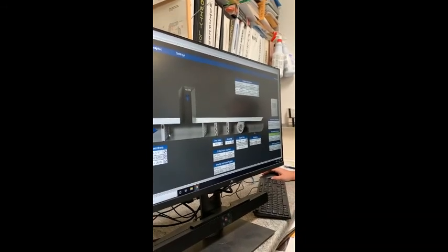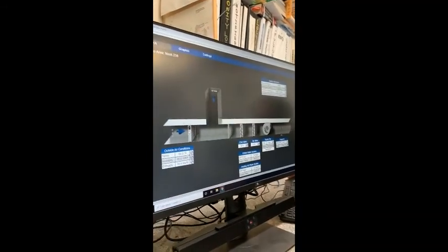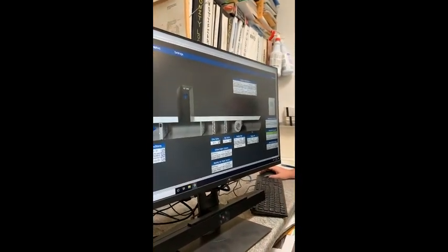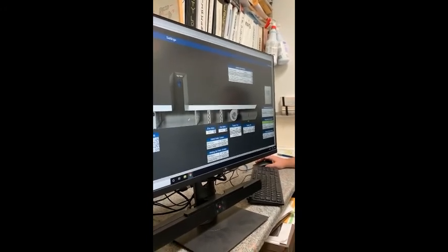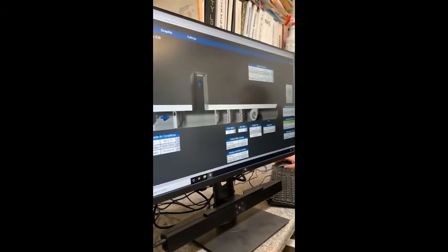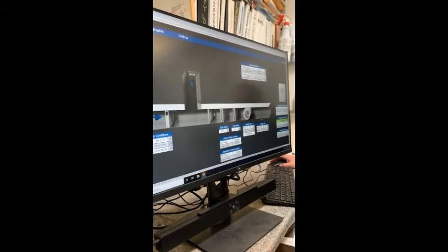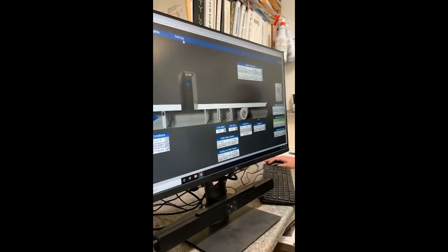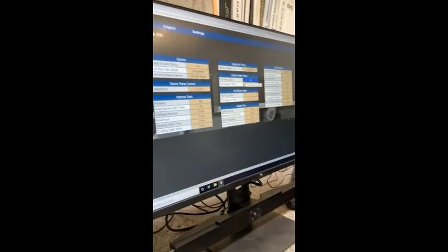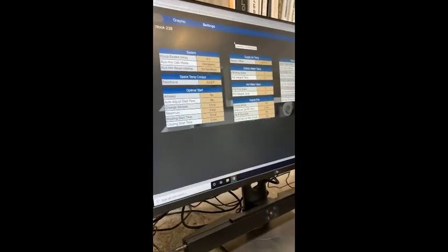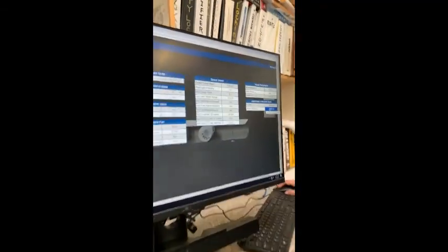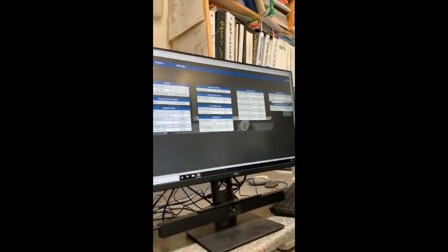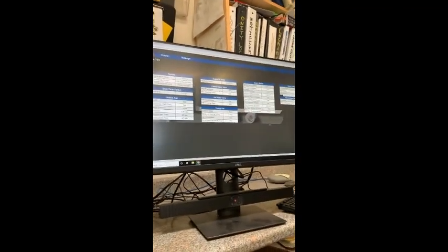We do not control an outside air damper for these. They were all hand balanced for a minimum outside air. There's no filter status. There is a runtime maintenance reminder. Right here, right now the alarm threshold for the maintenance reminder is 10,000 hours of runtime. I don't know what you guys would want that to be. It can be changed.